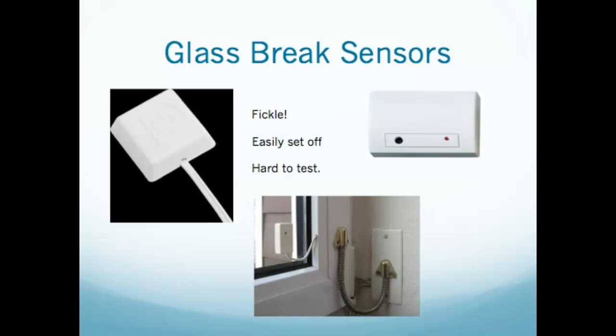You'll see them when you go into banks, and you'll see them when you go into some commercial buildings on the ground floor, glass only. You wouldn't put these on the upper floors. No reason to, really. I mean, yes, somebody could, I guess, Spider-Man up your building and go in through an upper window, but that's very rare. You will see these on the ground level. And normally you will see the shock sensor type. These will be mounted not on the glass, but normally on the ceiling. And you'll usually see a green light and a red light, and you'll be able to tell that that is a glass break sensor, a dual technology, glass break and a shock sensor.